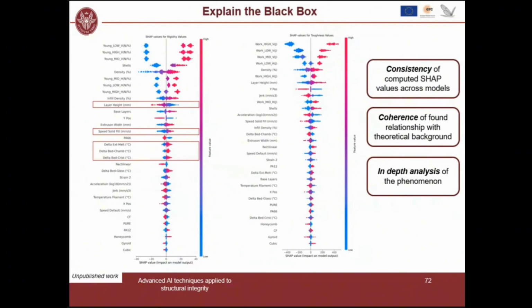So somehow that increased the crystallization inside the polymer. So it changed the macrostructure inside the polymer. Of course, you have to somehow give an explanation to those numerical values. But as a material scientist, you can do that. And you can do that here with polymers, but you can do it also with metals. And of course, here, by increasing the temperature of the heat bed of the print head, it increased the adhesion, and so it increased also the rigidity.